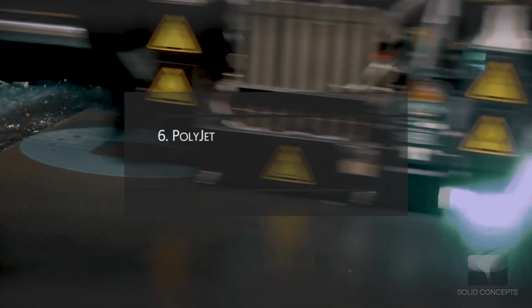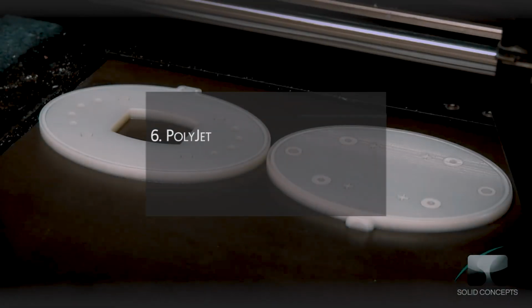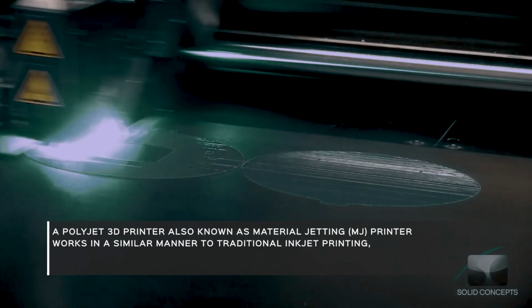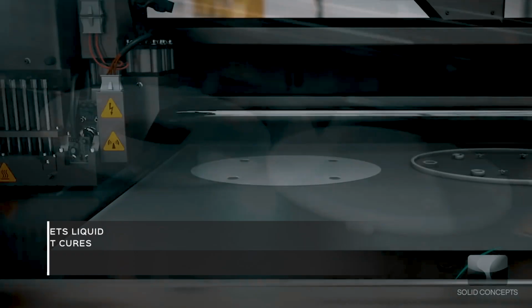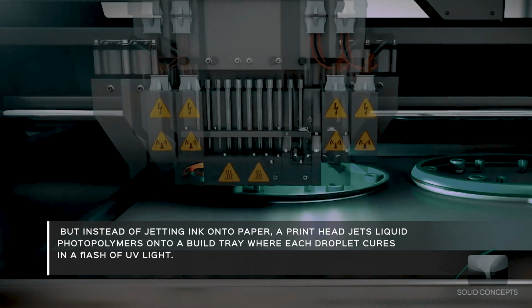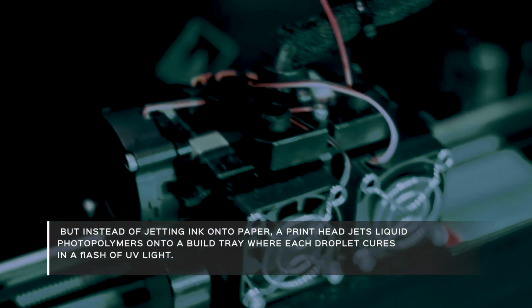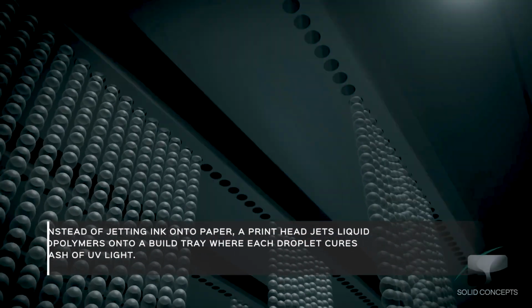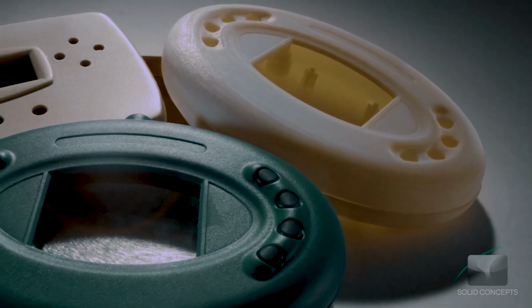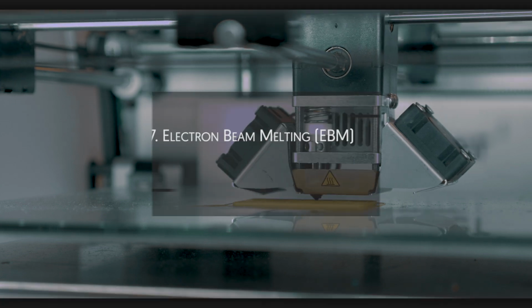Polyjet. A polyjet 3D printer, also known as material jetting or MJ printer, works in a similar manner to traditional inkjet printing, but instead of jetting ink onto paper, a printhead jets liquid photopolymers onto a build tray, where each droplet cures in a flash of UV light. It's one of the fastest and most accurate 3D printing technologies currently available.